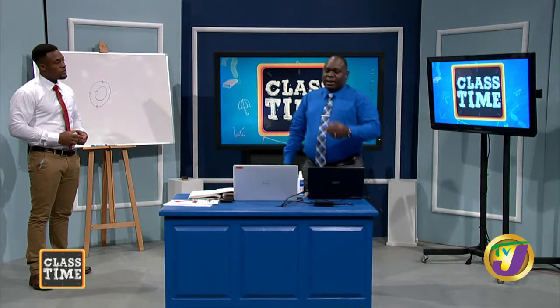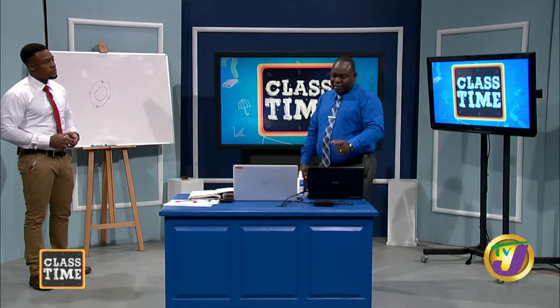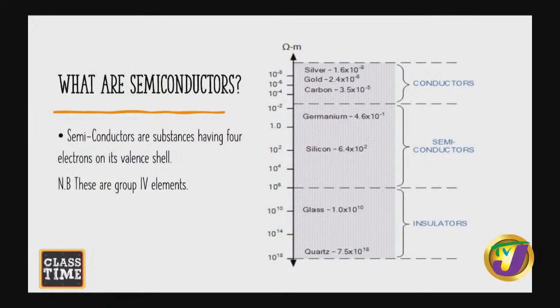If we look on our chart, you'll notice that we have a resistivity chart. When you look at the conductors on a resistivity chart, like silver, gold, and carbon, they have a very low resistivity, times 10 to the negative 8, because these are materials that allow current to flow easily through them. Then if you look at times 10 to the 2, times 10 to the 4, like silicon and germanium, which are commonly used semiconductor materials, you realize that it is midway.